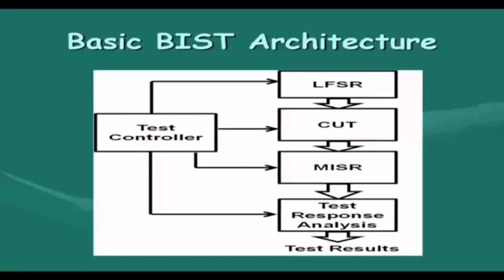So, internal testing technique means we have got the test pattern generator and the response analyzer inside the chip. So, we have basically the BIST type of environment, the built-in self test type of environment. So, the basic BIST architecture is like this, as we know that this is the circuit under test.